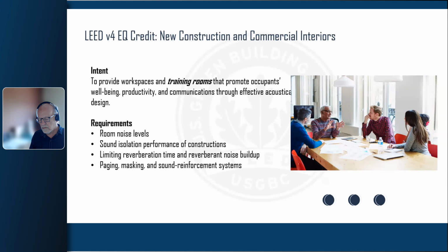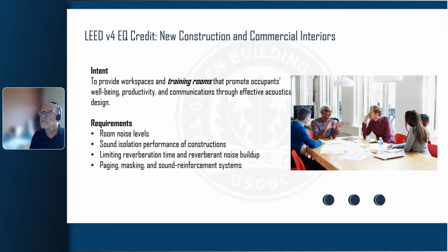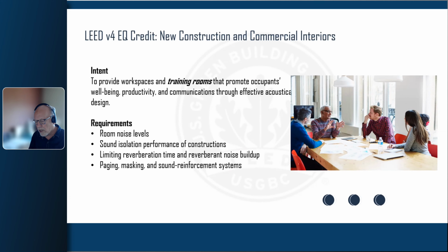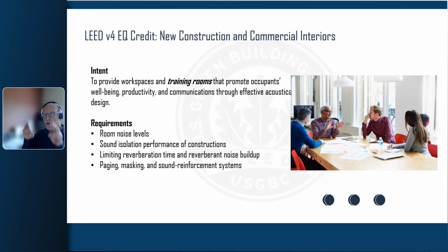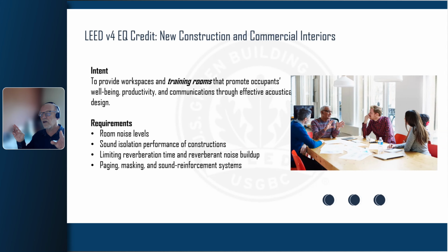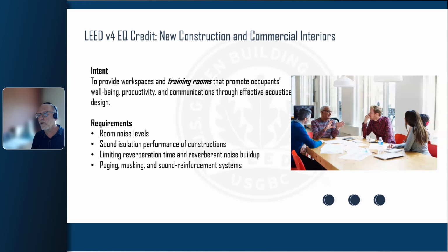Under what conditions is acoustical weather stripping and automatic door sweeps merited? I would say in every case. You don't want to apply it to just any door, though. We OEM with a lot of different seal manufacturers, so there's some very good product out there, but you can't buy an acoustic seal and put it on a conventional door and expect to get high performance.